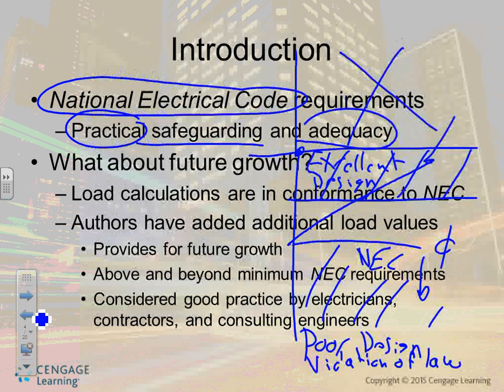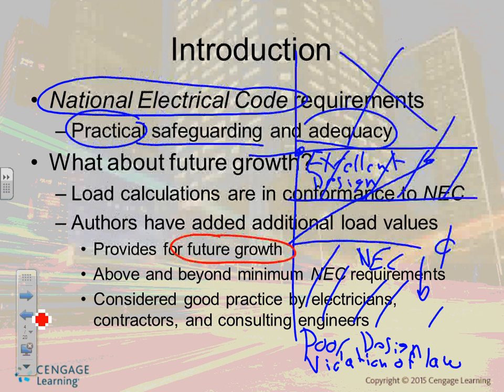So when you're doing your calculation there, guys, you have to take into consideration the future growth of the building. A lot of people go above and beyond what the NEC code book allows you to. And you guys are right in here in the consulting engineer department. So if you, Chad, were circuiting 10 receptacles per circuit, and you go to an engineering firm, they're using 4. That's not wrong. Remember, they don't want to be sitting on the zero point.